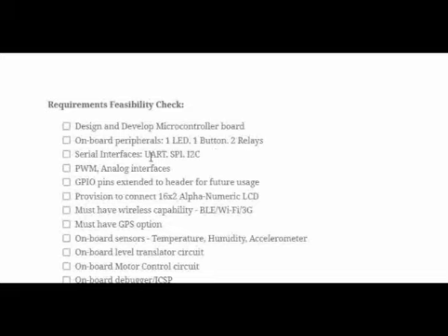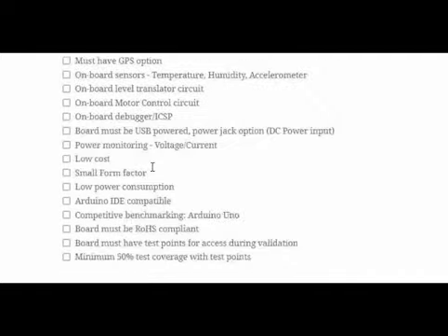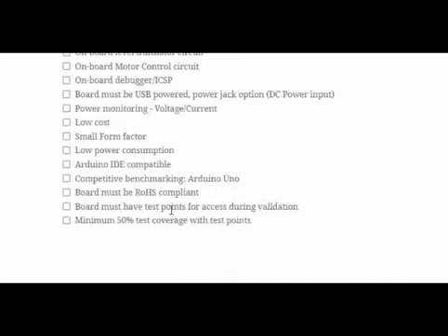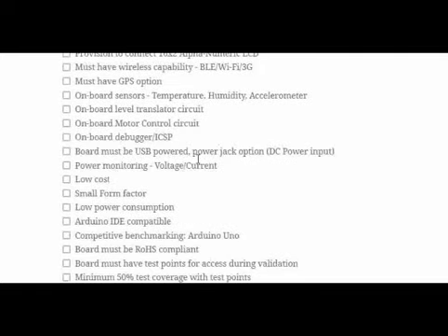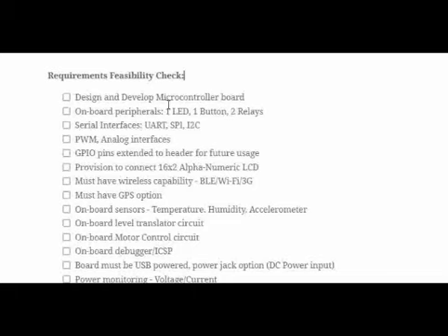So easily achievable. And then the requirements were to have UART, SPI, I2C, right? Definitely these are there in the Arduino chipset, right? So we are going to make an Arduino IDE compatible board, and we are going to use the ATmega chipset. So that means UART, SPI, I2C are present and they can be used.